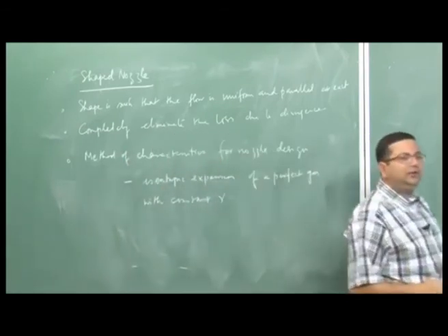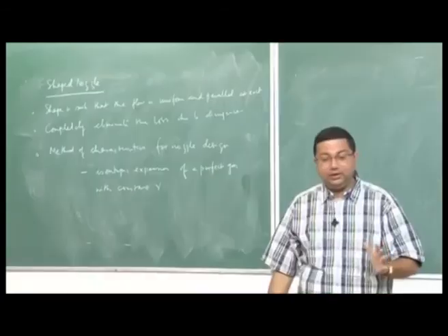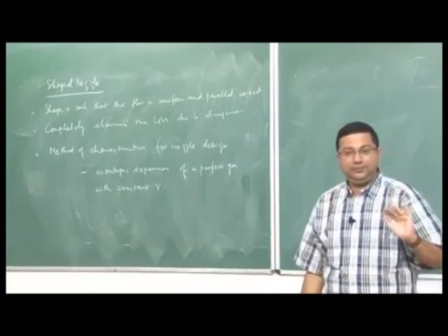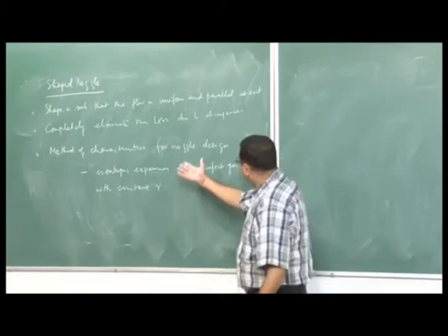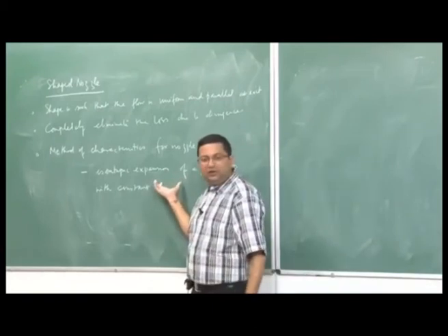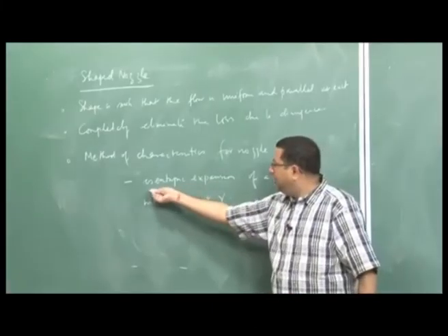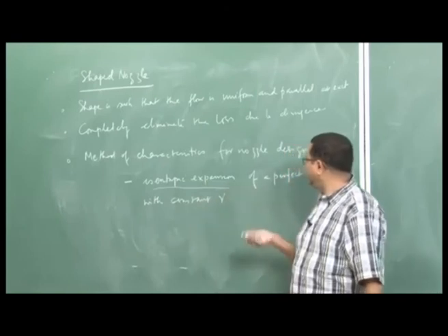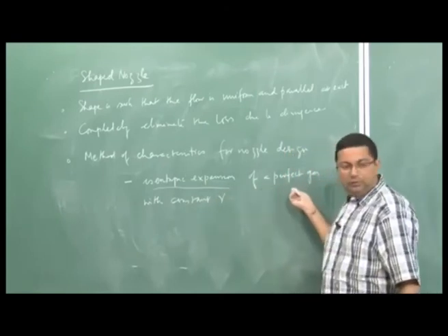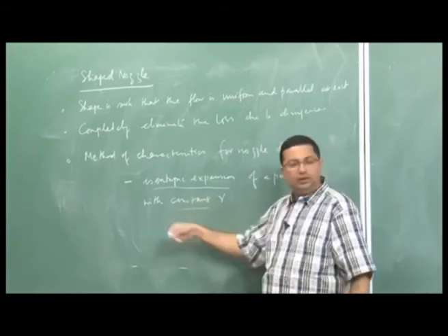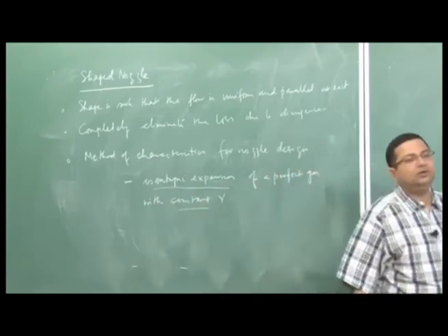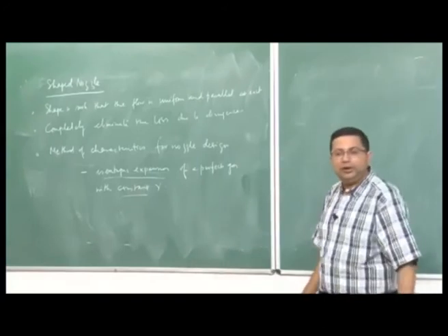So, method of characteristics actually assumes the flow to be isentropic and expanding. These are the two things that are required for using method of characteristics. So, here we have an expanding flow in the nozzle. So, we essentially maintain isentropic expansion, we assume the fluid to be a perfect gas with a constant value of gamma, and we can use method of characteristics to get the proper acceleration.